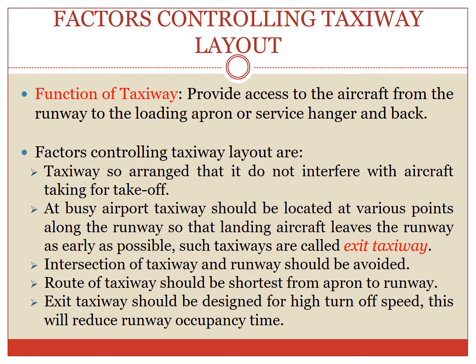Now moving forward to the factors controlling the taxiway. In planning the layout of a taxiway system, these are some of the factors that should be kept in mind. Taxiways should be arranged so that the aircraft which have just landed and are taxiing towards the apron do not interfere with the aircraft taxiing for takeoff.